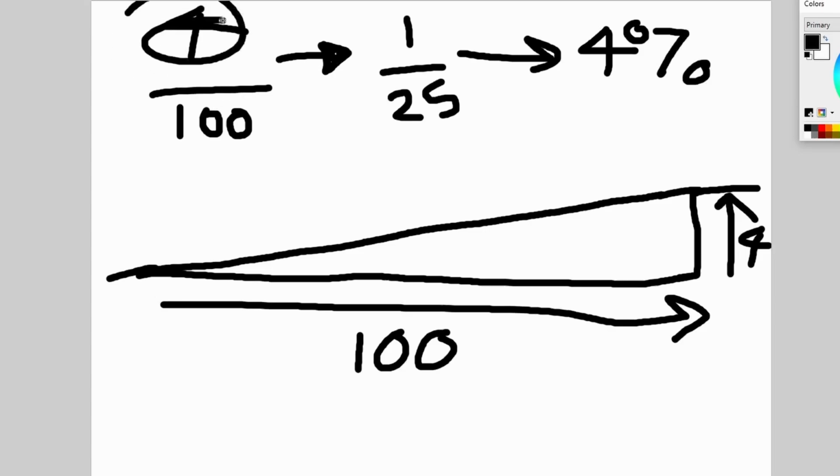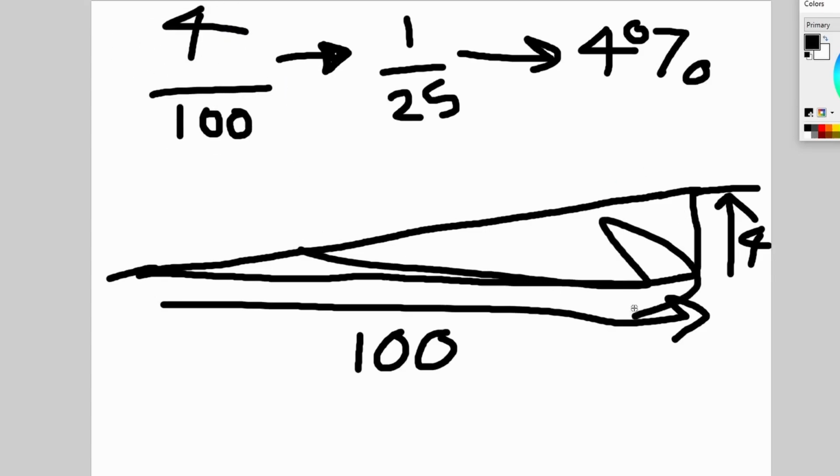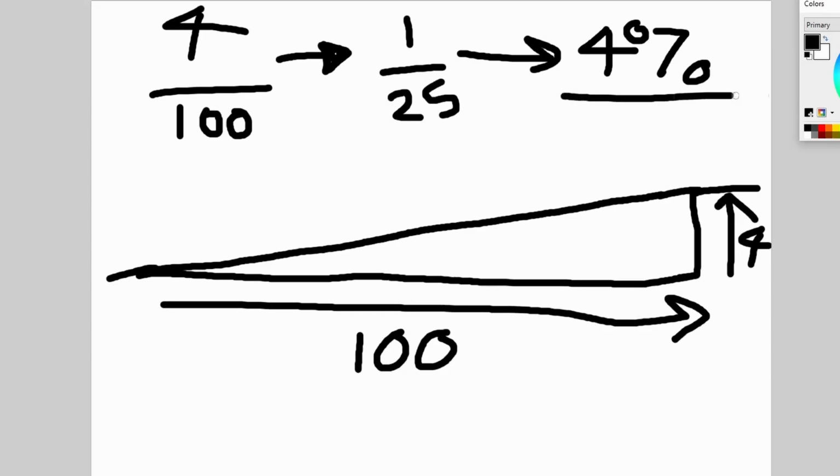We went 4% of 100 feet up each 100 feet. And 4% is very steep for trains. The steepest mainline grades that the railroads typically try to keep to these days are in the 1.5 range. Obviously, there are some that are steeper, and many famous ones that are 4% or even more, even on standard gauge. But 4% ends up being kind of the end-all be-all for a lot of narrow gauge, right?